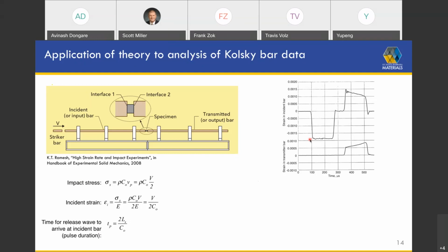We can think of those obstacles as being athermal. And if it's athermal, the implication is that they're strain rate independent, or at the very least strain rate insensitive. So with FCC materials, you do find there is this extended domain in strain rate where the strength is essentially constant.